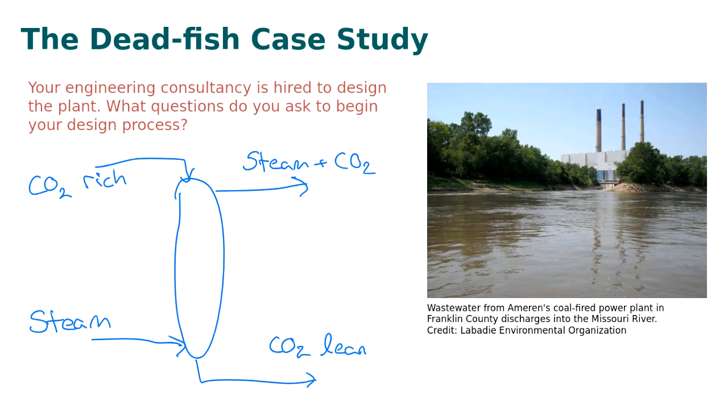And the question is, why has the efficiency of the stripping column dropped? And you might think that perhaps some of the trays have fouling on them, or the inside of the column is starting to corrode. There could be unpredicted perturbations in the flow rates of the two inlet streams. This is basically where a chemical engineer would generally start questioning.